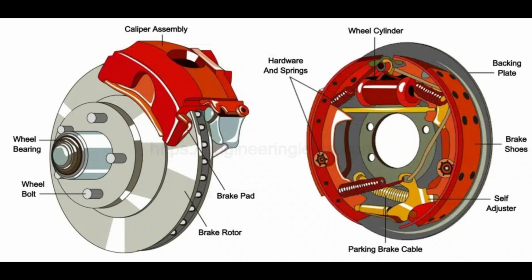For instance, in regenerative braking, much of the energy is converted into electrical energy, which can be stored for later use. The eddy current braking system uses magnetic fields to turn the kinetic energy into an electrical current in the brake disc, blade, and rail, which is then finally converted into heat.